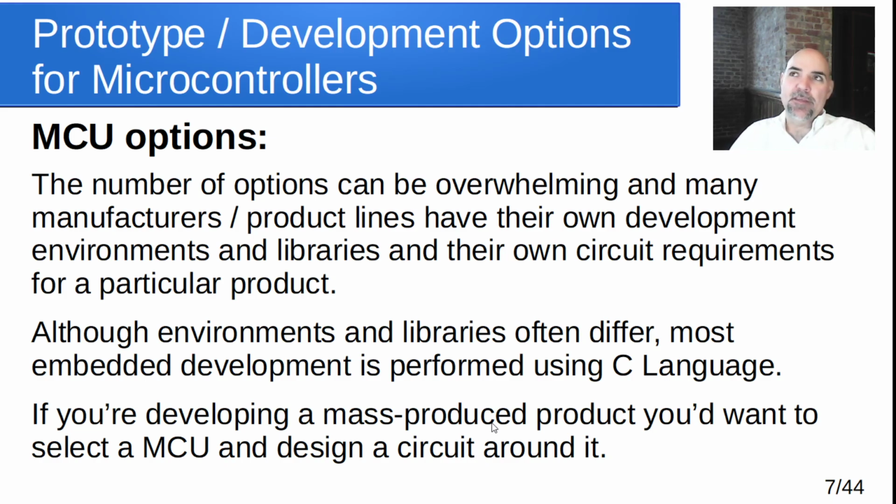And one of the things that most of the development for microcontrollers has in common, even though the environments and libraries can be significantly different, almost all development at the embedded level for microcontrollers is done using C language. Now, if you get to some of the higher end microcontrollers, they might run a version of Python or something else. But for the most part, all microcontroller development is done in C language. And the reason for that is C is really in a sweet spot for giving you low-level access to do things at kind of the hardware level, unlike other languages like, I don't know, Java comes to mind.